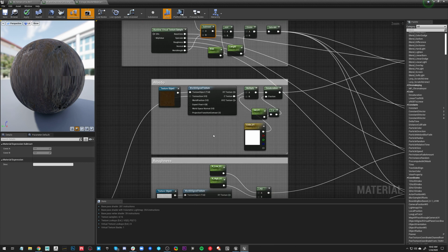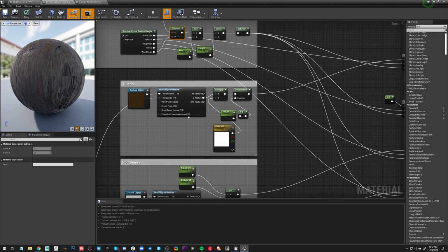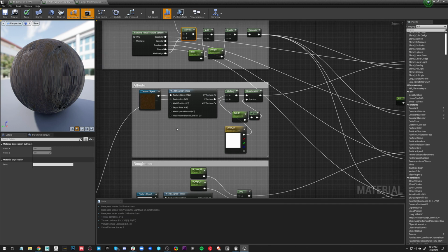So say you wanted to automatically have rock on really sharp angle surfaces, so as it gets really steep, it's going to display rock, then you could do an XY texture. That way, whenever it's super steep like that, you have rock coming in and projecting on the XY axis. But if you wanted to do that on everything, that is probably going to absolutely murder your performance.